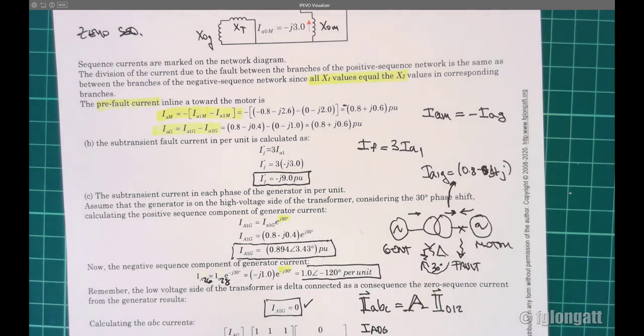I highly suggest that you reflect on what is happening with the positive, negative, and zero sequence impedances inside your system, because those properties will allow you to draw very good conclusions. Also, if you are taking my classes on power system protection, having a full understanding of those symmetrical components will help you a lot in the future for overcurrent protections, okay?